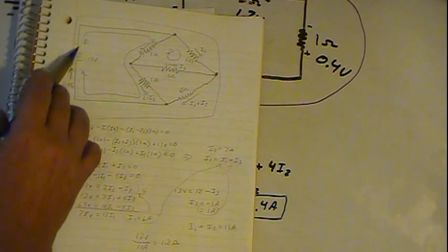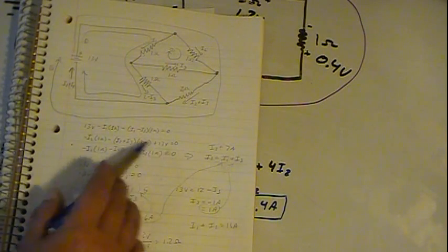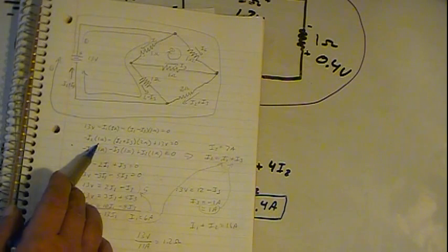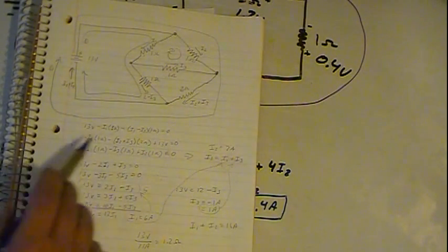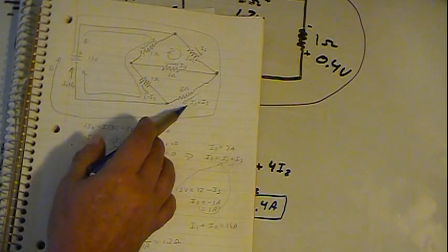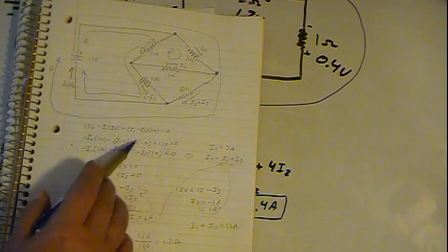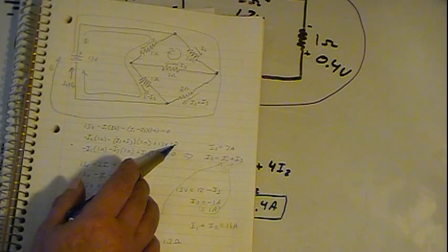The second loop, we'll have our 13 volts, minus I2 times 1 ohm, minus the quantity I2 plus I3 times 2 ohms, and then plus 13 coming back,